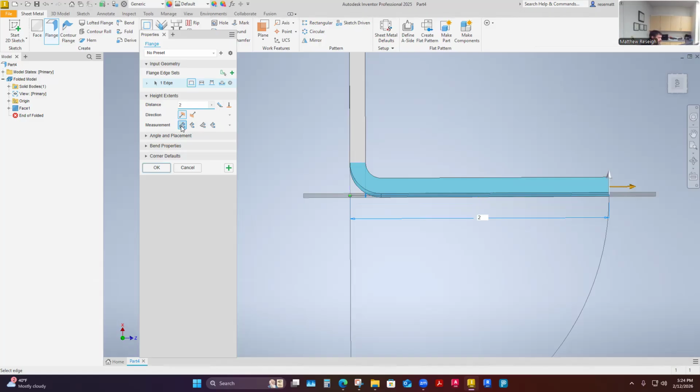I really have to fine tune what my settings are because every box I expand here gets pretty extensive, right? So that's all I can select here on the height's extent. Like, which way am I pulling the dimension? Which way am I folding around and what's that length? And then I go down to this next dialog box and I get even more control over the angle and the placement and how that angle affects the length. This is additionally complicated, but he does a 60-degree bend first.